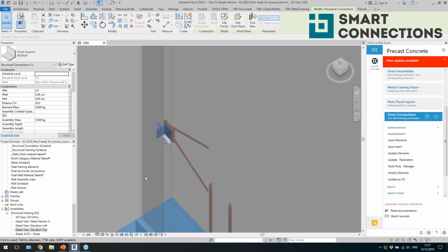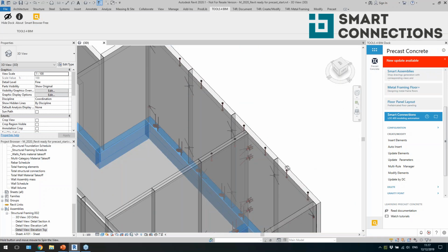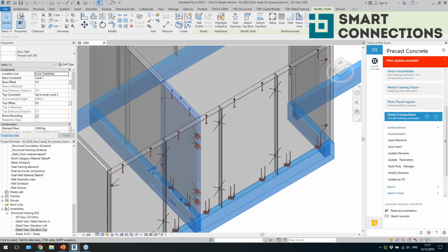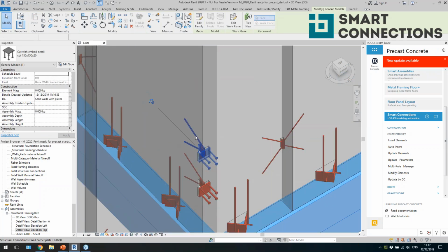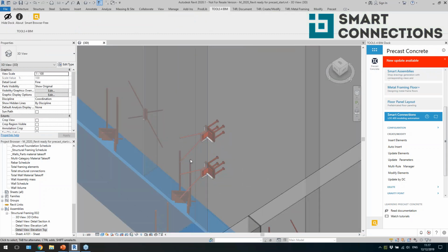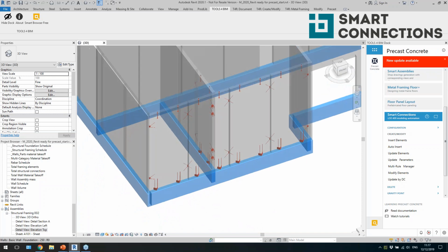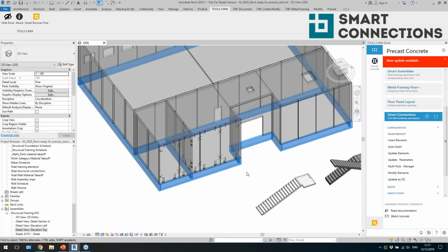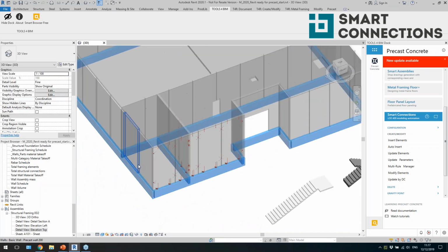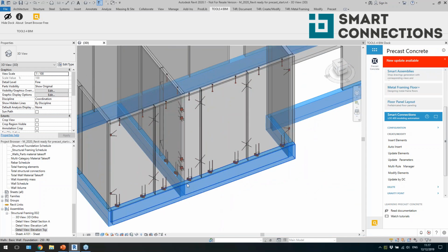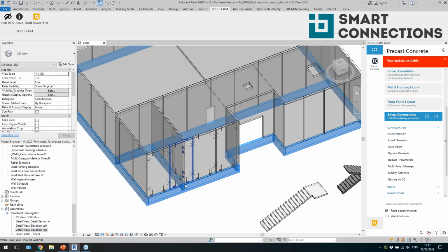And then I have a loose detail over here, right? And the same in the intersection position. So it automatically recognizes that this is intersection. It's adding these plates, and I have this kind of connection created between my wall panels automatically, right? So I don't need to do that manually, like with Revit. I would need like several hundreds maybe of these details. So it's really quick way to distribute them.